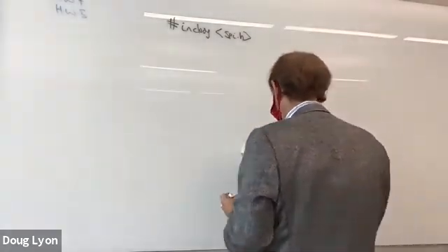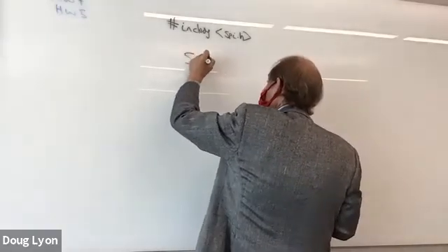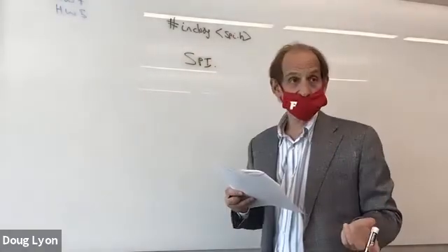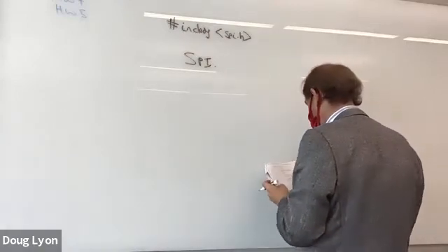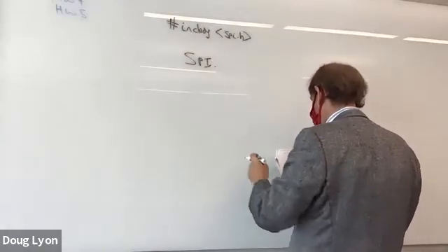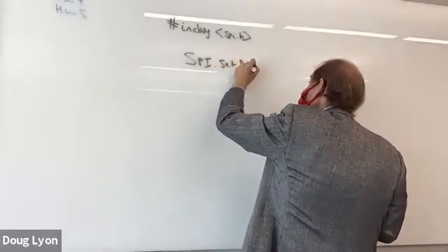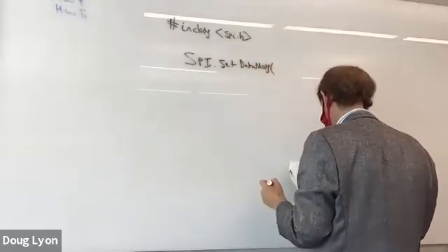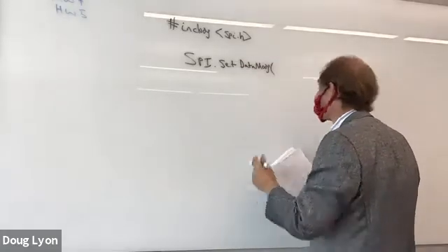For example, you'll be able to do SPI dot, and then issue commands to the serial peripheral interface. For example, you could say SPI set data mode. And what that'll do is you might say SPI mode 0, that's built in.